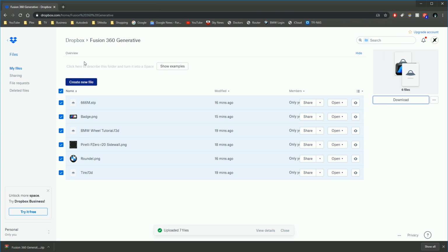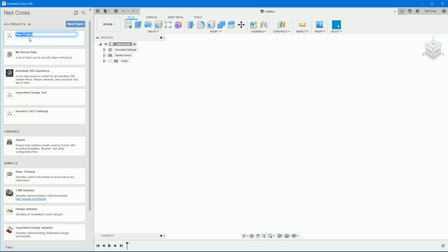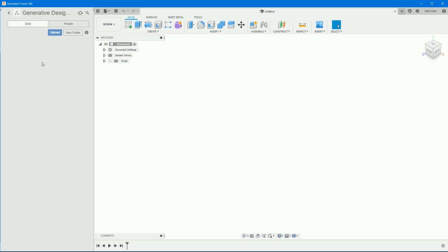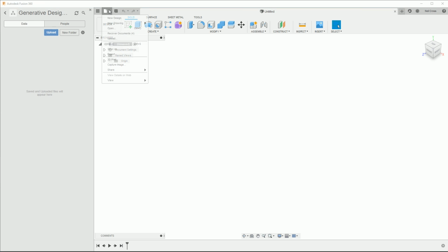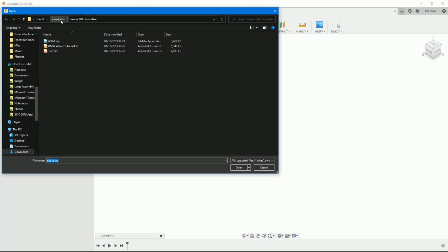Right, so hop on over to Fusion 360, and then we need to set up a project. So I'm going to create a new project, and I'm going to call this Generative Design YouTube tutorial. You don't have to create a new project, you can use whatever project you've got, but double click into that, and then we're going to go to File, Open from my computer, browse to the Downloads folder, go into the Fusion 360 folder that I've given you, and then double click BMW Wheel